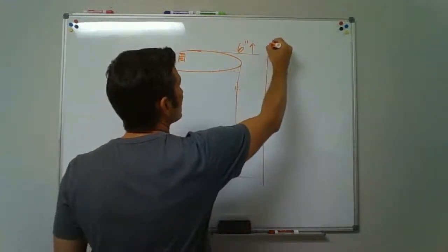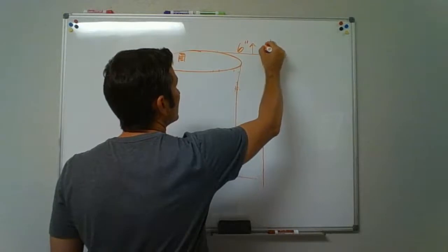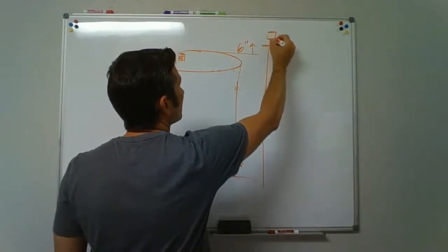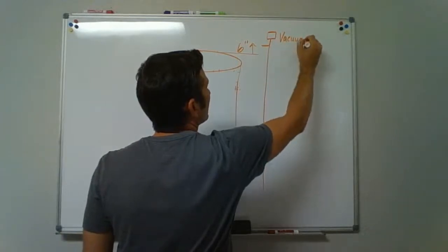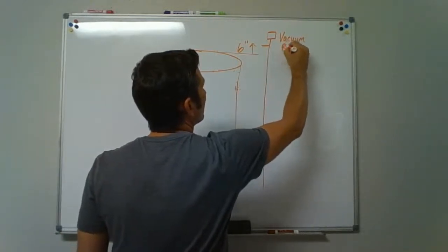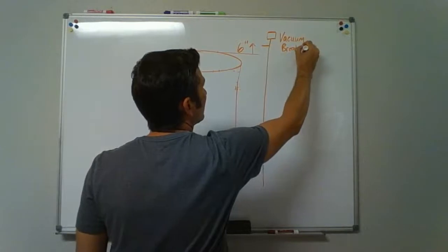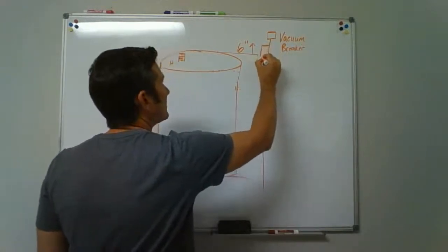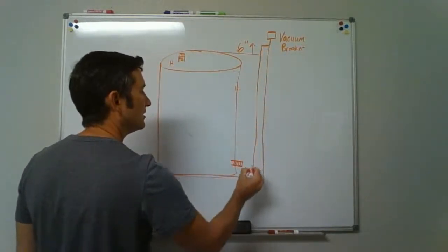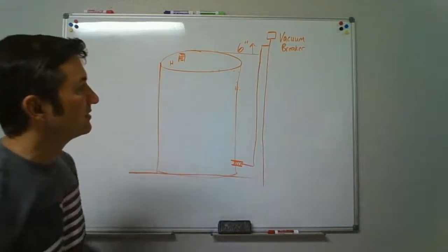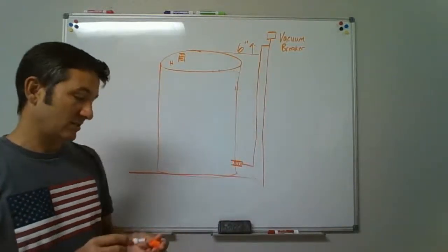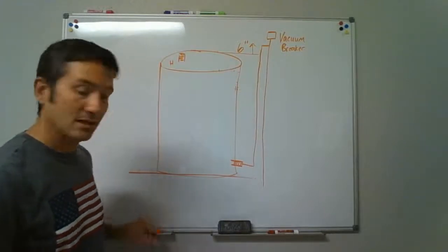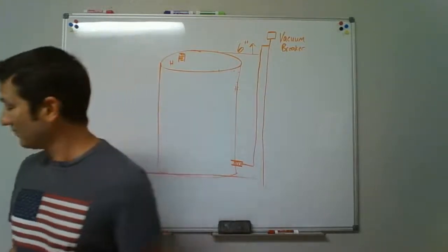So we're going to go up six inches, put a T in the line, install a vacuum breaker, run this line back down, and now install to the side of the heater. Little extra piping that you need with a vacuum breaker up on there, at least 6 inches above, to make that legal for a bottom-fed water heater.